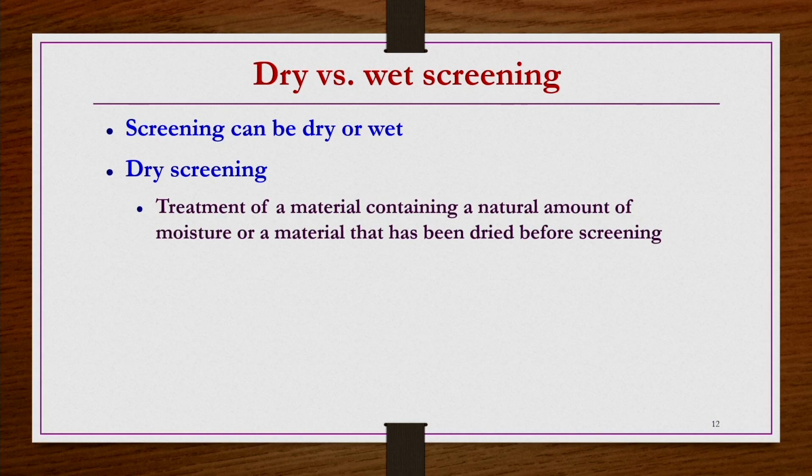Sometimes in your samples, too many finest particles are there that you do not want in your case, or sometimes those finest particles are of much higher value. As I mentioned, sometimes even the finer particles may not pass through the coarse openings, because they are retained between the particles, or because of blocking of the coarser screen apertures.